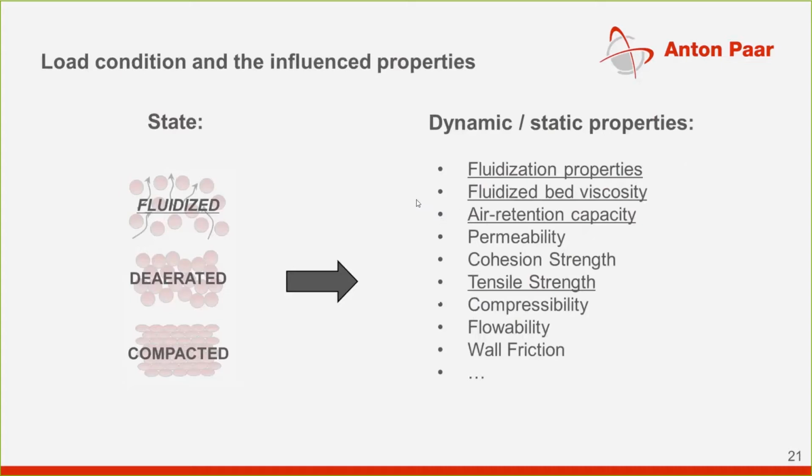Specifically for the fluidized state, we can look at fluidization properties. We can look at fluidized bed viscosity. It's possible to look at the air retention capacity of powders. And it's also possible to measure the tensile strength.